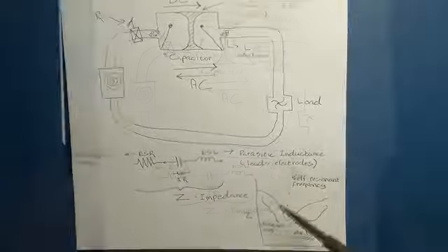Now, the first part of this curve has a high impedance, but what's that due to? That is due to dielectric loss. Going back to our analogy, let's say we've got this bladder over here, which is also acting as our dielectric. If it has a stiffness, and you imagine the water pulsing backwards and forwards slowly, it's going to have a hard time moving that if it's stiff.